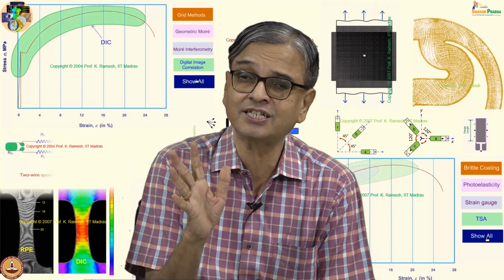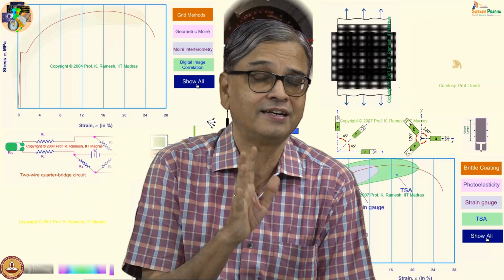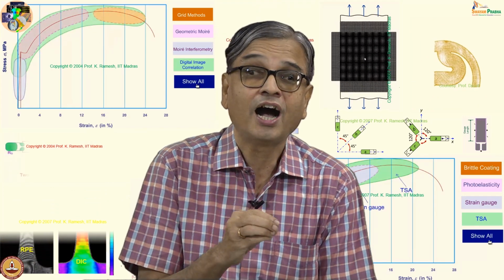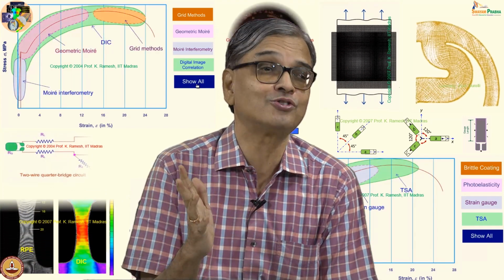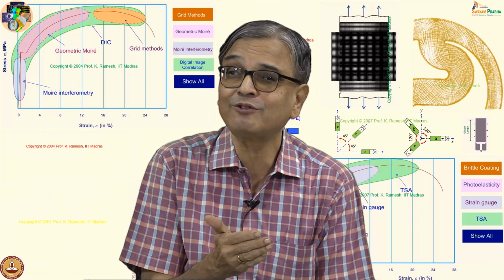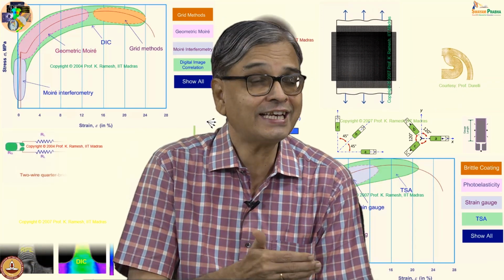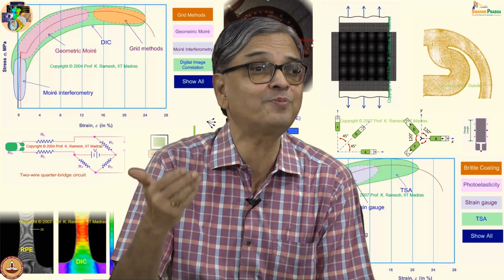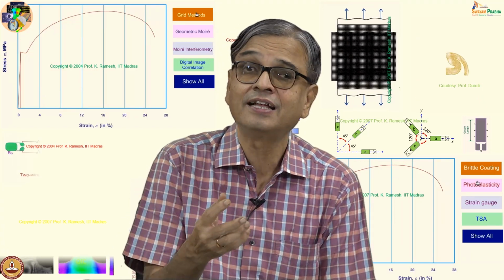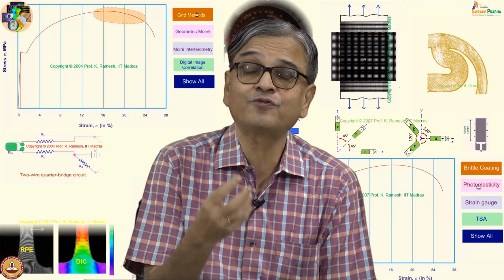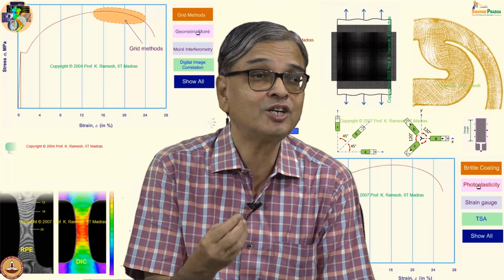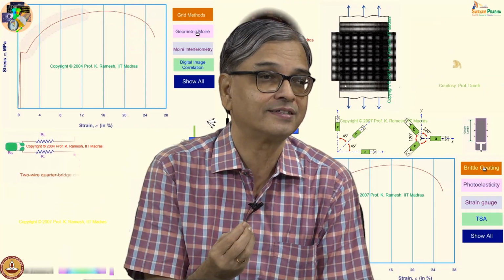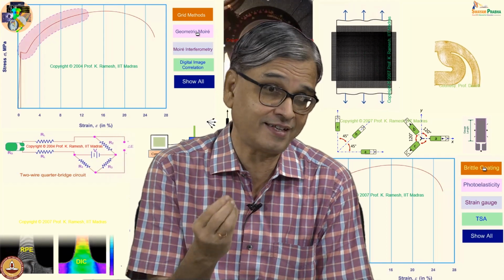See, one of the challenges when they discovered strain gauge was how to measure microvolts, because I am going to have micro strain. So, the electrical change also will be in very small quantity. So, people needed amplification circuits for them to have measurement of these very small voltages. You have to recognize that is 10 power minus 6.